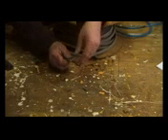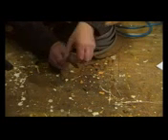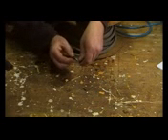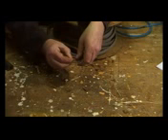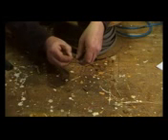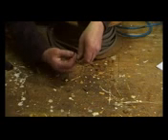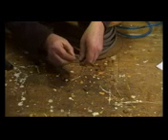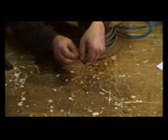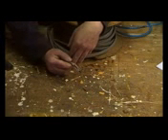So let's zoom in. The cable size is to do with the solid copper core. So it's the cross-sectional area of the copper. You can't just measure this, because there are 7 strands there and there's a load of gap between them, so you have to measure each individual strand and then do a bit of arithmetic.